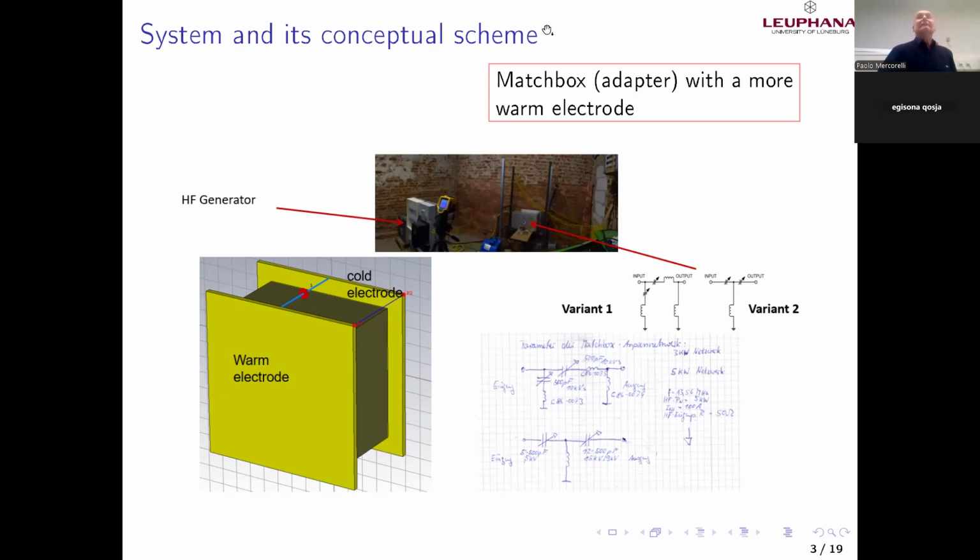Using a capacitor, which for the engineer is quite clear, and applying voltage on these two electrodes, we have a current inside, and this current generates a temperature, and the temperature is able to desiccate, to eliminate the humidity. I don't want to insist on this part here, but in any case, this part is there to adapt the impedance. That for the engineer makes sense. For the non-engineer it is not relevant.